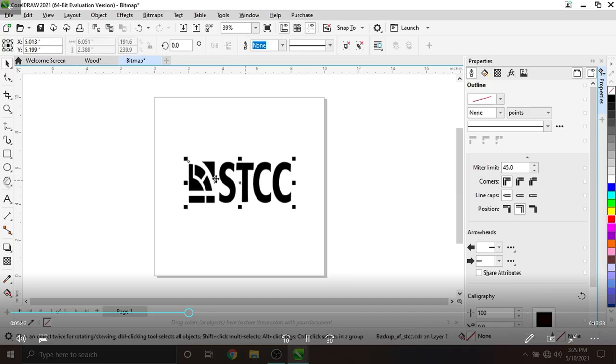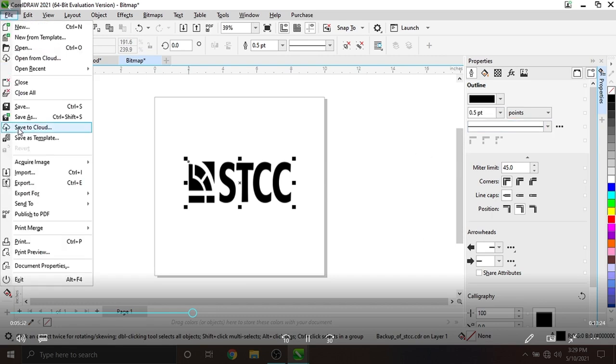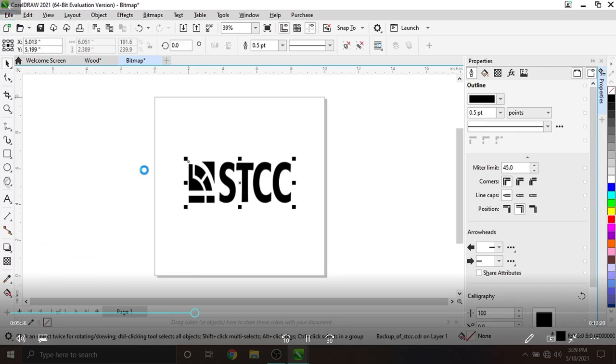And with bitmaps, you can grab anything from the internet or a picture that you have. And we're going to make it 0.5 also. And we're going to keep it black so it prints at the 50-50 for wood. This is for wood burning, but again, go back to print. Do the same thing. Go into the preferences or the cog, whatever version of CorelDraw you're using.